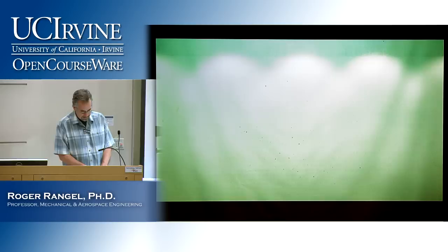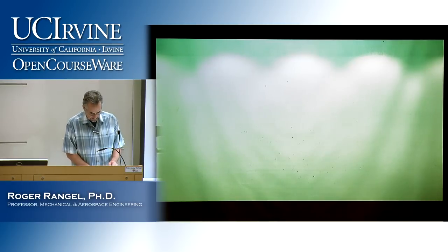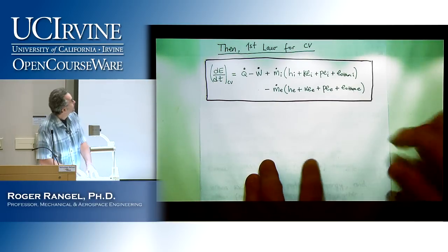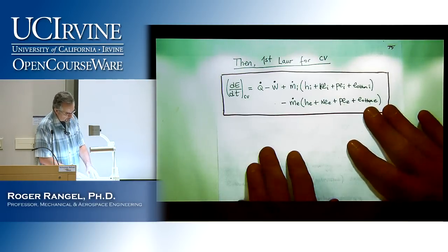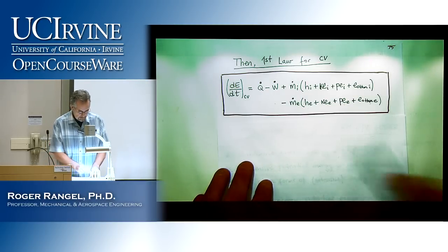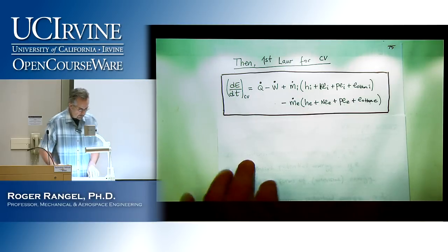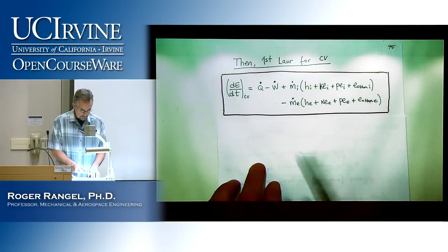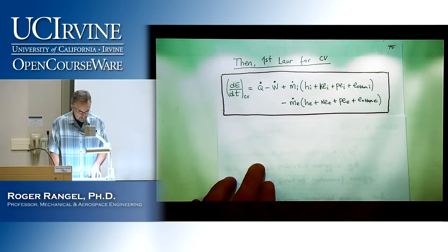As the name implies, what is happening is that now we cannot make the assumption of steady state. So when we wrote the first law of thermodynamics in general for a control volume with all of the terms, the problems that we have done so far are such that the energy inside the control volume was constant in time, and therefore its time derivative was 0.